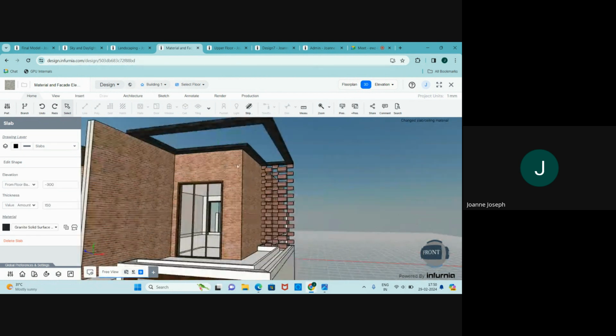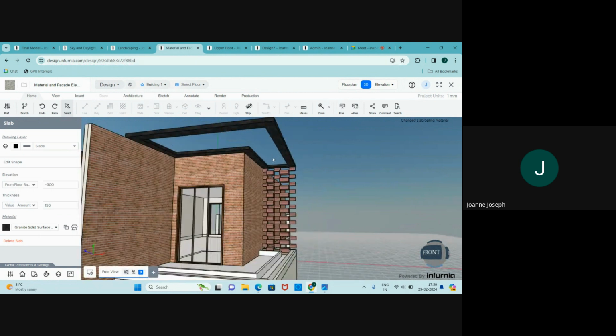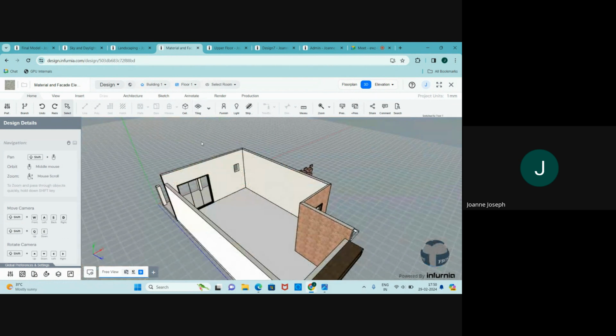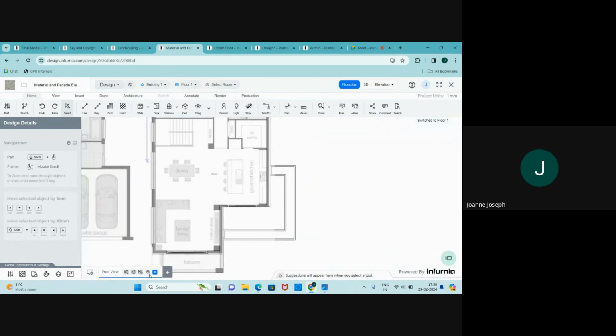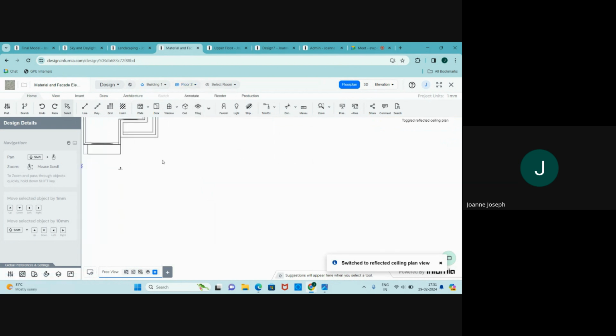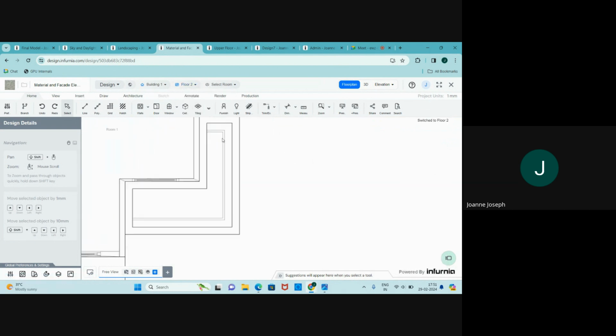And to create those pergola lines, you can actually use the beam method for this. By that, what I mean is when I go to floor plan once again, let's say I go to floor 1, I go to floor plan here, and here in this view, I switch on, I go to floor 2 instead.